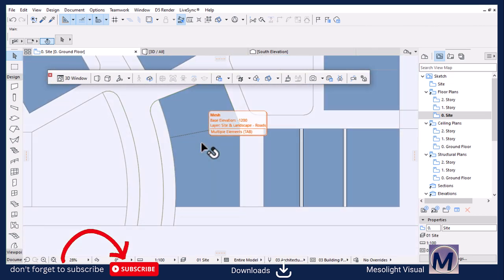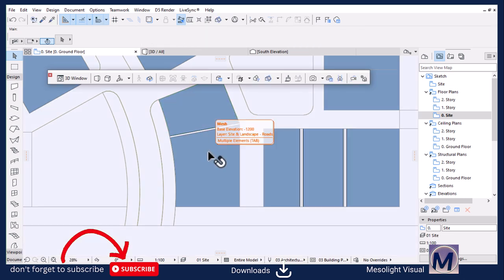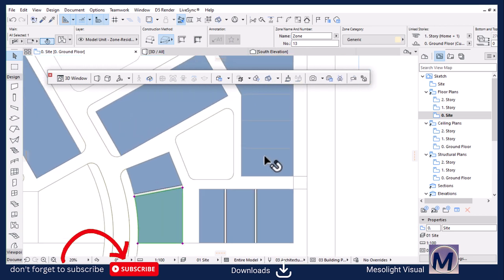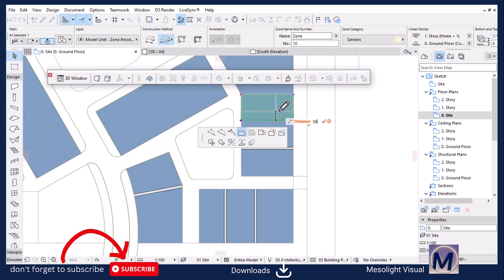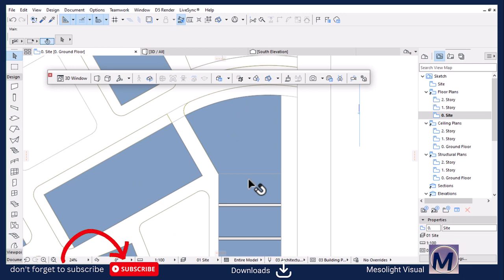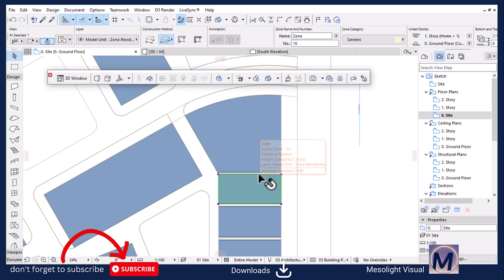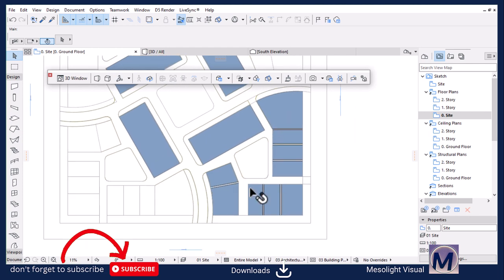Same to this one. Let's Tab and then offset the edge. Do the same on this one. Tab, then move it down by 500. Let's move on to this. Tab, 500. Tab, 500, just like that. Tab for this. That's the last one. 500. Perfect. Now we have the residential section complete.